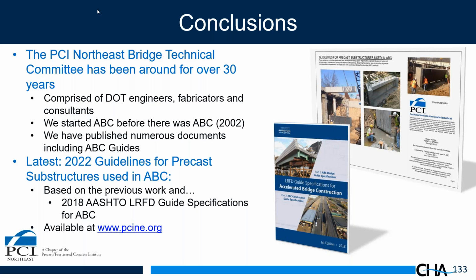In cast in place construction, we have construction joints in every structure we build, and sometimes we expose those joints while they're underwater. The same precautions would follow here. There's no reason you couldn't have one of these connections be underwater in the final condition. The durability has been proven to be equal to the cast in place construction. Okay.